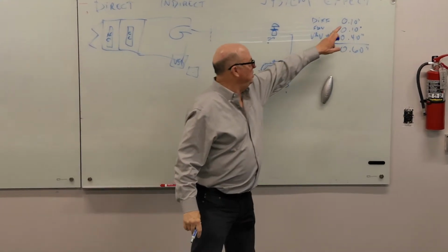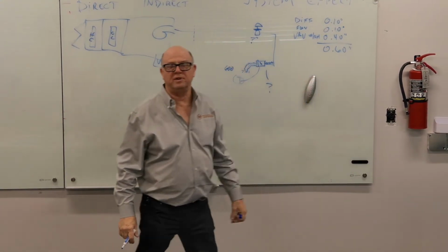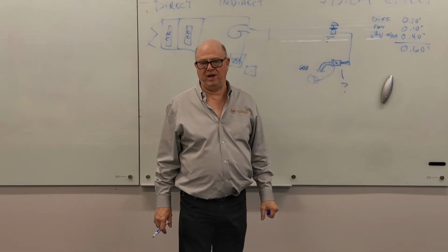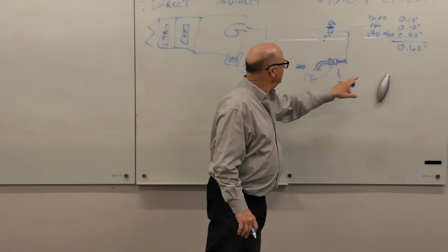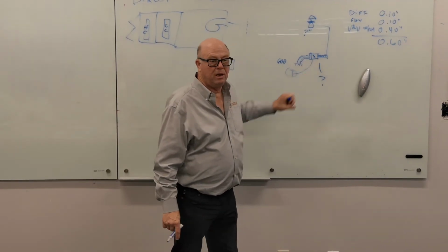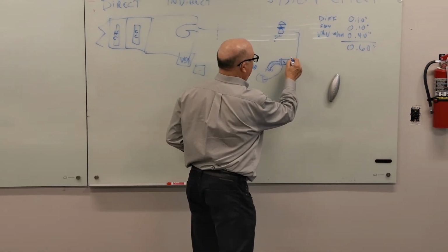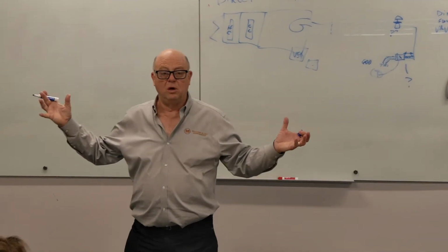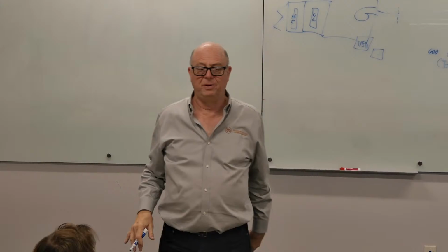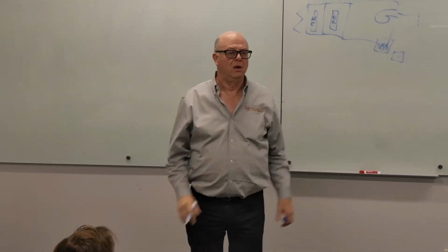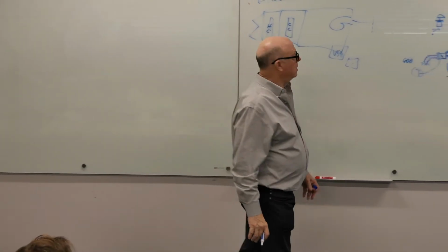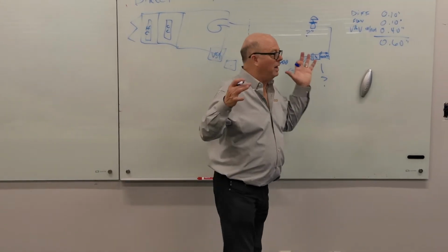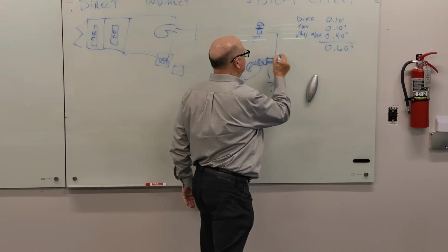You have to have this much. If these three numbers are accurate, it'd be 6/10 of an inch. We often get by with 5/10, but okay. So we got 6/10 of an inch at that point. Well, then how far this thing has got to run is a factor. If it's got to go a long ways, they're going to use spiral and they're going to wrap it. If it's a short little amount, they might not even use metal duct. But you've got that high side, whatever that is. I'm just going to arbitrarily say that that's 1/10 of an inch.